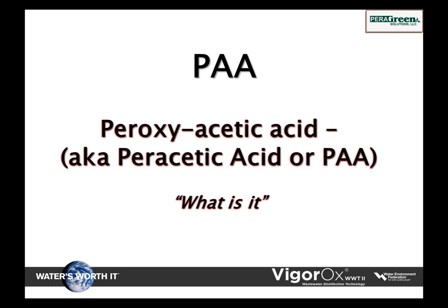Basically, it's an equilibrium reaction between hydrogen peroxide, acetic acid, and water. Peracetic acid is formed after a 4 to 5 day curing process. Heat's released, and what occurs is an equilibrium at different percentages. You can have 12%, 15%, 18%. Originally, they were starting at 36%, but found it was very unstable. For the municipal industry, it was found that 12 to 15% or 16% was a good product mix. It gave you the ability to feed at lower volumes and was applicable to municipalities. The food and beverage industry uses about a 5% mixture.